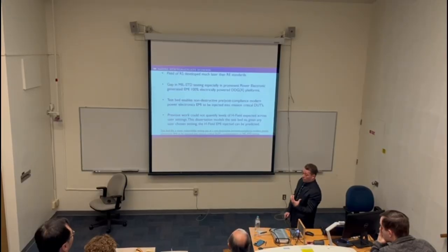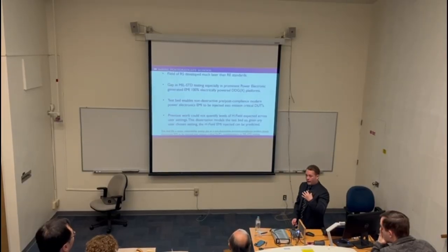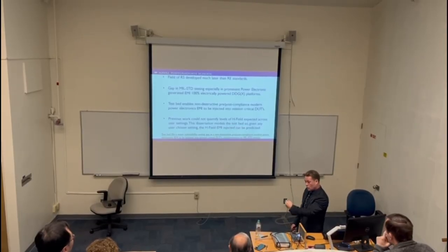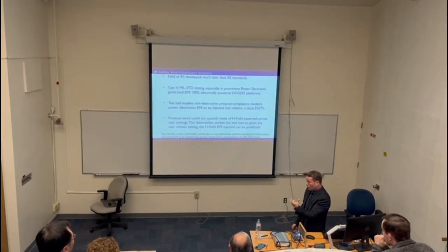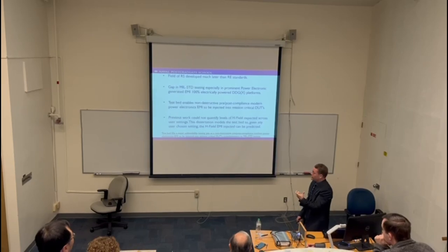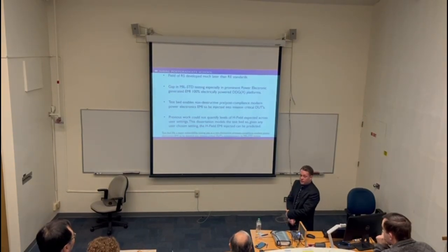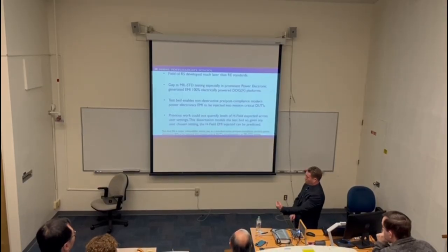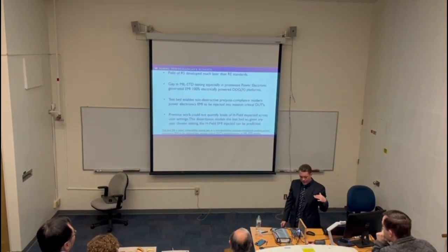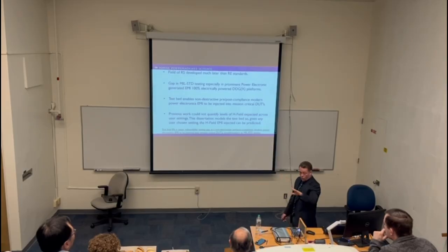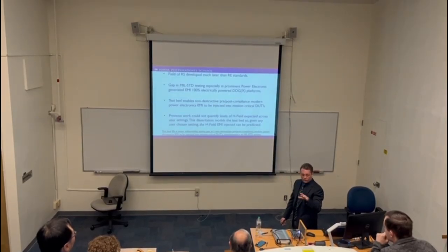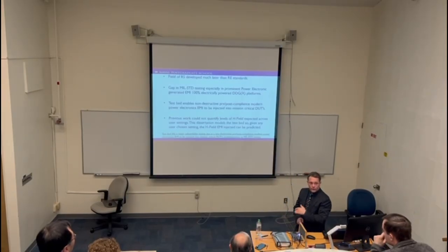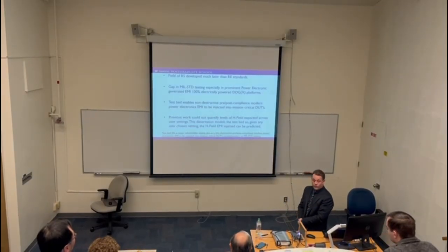So what we're modeling, again, is the power electronic spectrum. We chose 1 MHz to 100 MHz, which is a very vulnerable band, obviously not captured in the MIL standard either, and it simulates some of the radiated EMI that's coming off of power electronics. In previous master's theses, we went through the whole process of proving that this causes failures in systems. On gate drive boards, we were throwing gate switching algorithms completely out of whack, and we were able to create failures.